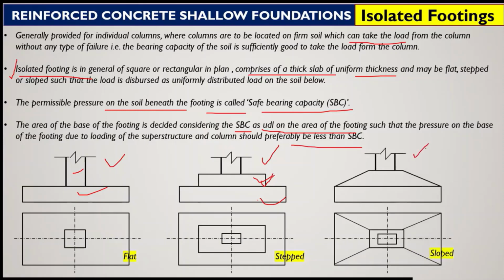Now sometimes we design this type of footing where we provide some slope for the purpose of economy, because we are aware that bending moment will vary as we move away from the column. So accordingly we can design the footing, and this type of footing will be a sloped footing. You will see that there is a slope, and this will be the plan of the footing.